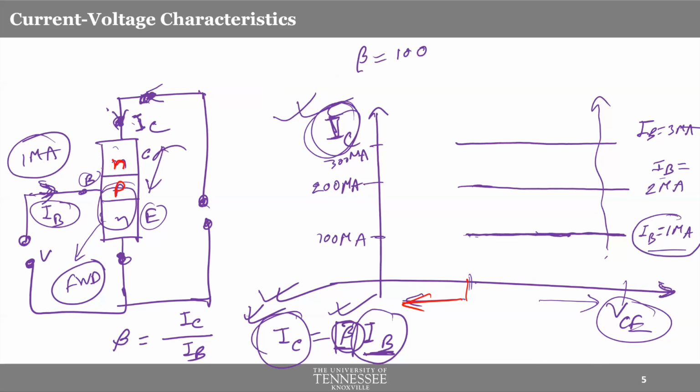And why is that? Imagine, just remember, there is a base voltage. Let me say that the voltage at this particular point was 1 volt. Let me take a random number here, 1 volt. And your collector voltage was, say, 5 volt. Now see, the voltage across this PN junction will be effectively 4 volt.